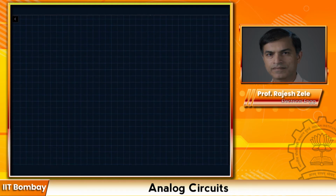So far we have done the common emitter and common base amplifiers. Now we have one more configuration left as the basic configuration for a single transistor amplifier. And as you would have guessed, it should be called the common collector amplifier. In case of common collector, we would have the collector connected to some DC bias, and input is applied to the base and output is looked at the emitter of the device. So let's draw the schematic first.